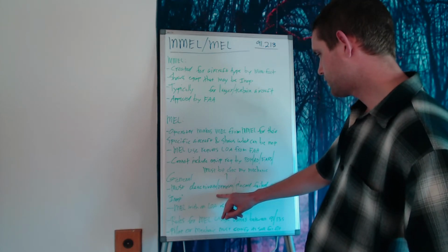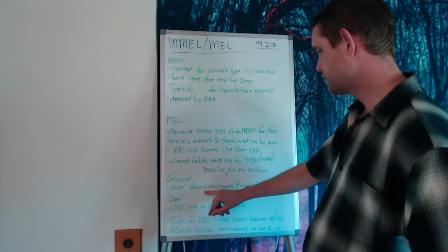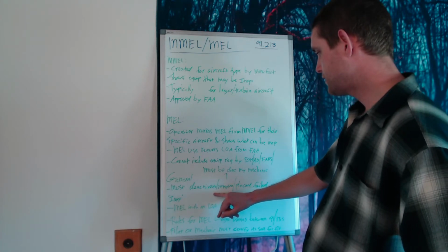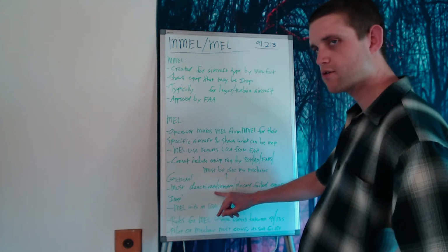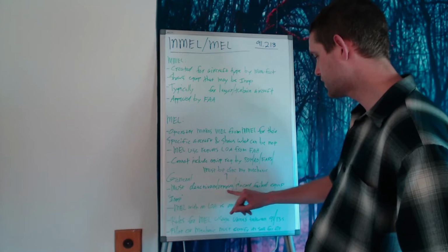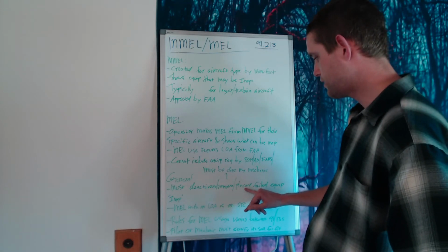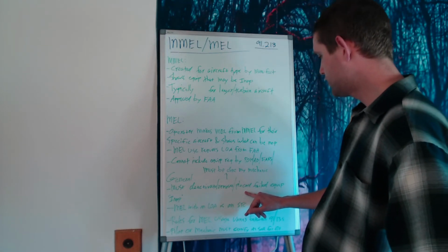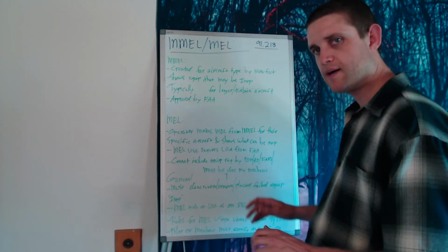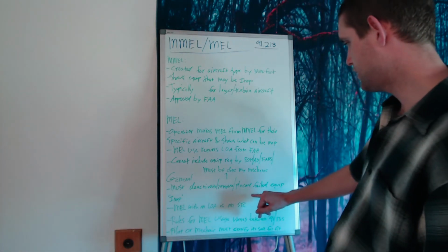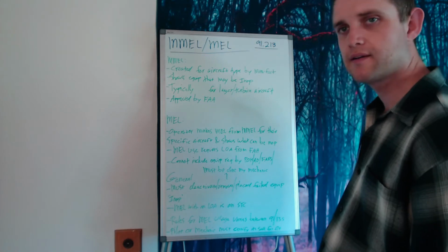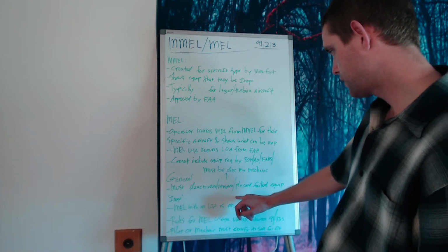First, you want to deactivate and/or remove the piece of equipment, and then place a placard that has the word "inop" or "inoperative" on it over the control switch or button for that piece of equipment.